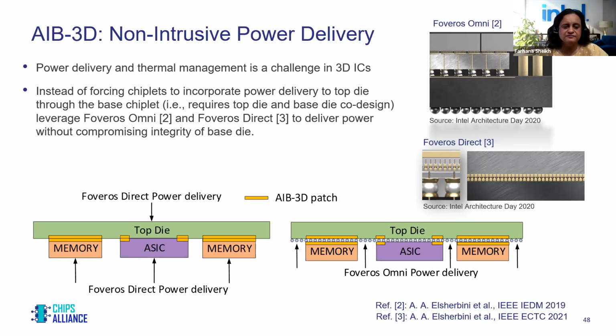You don't have to make Swiss cheese out of your base dies. Using Foveros Omni, on the right-hand side at the bottom, you can deliver the power in between the base dies that are shown here, the memory and the ASICs, using the larger bumps as shown in the top picture.